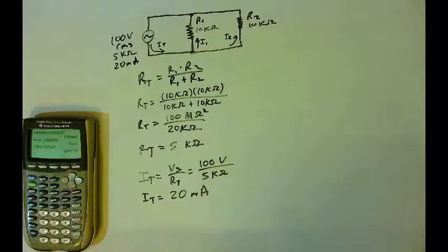The RMS value, being the equivalent DC voltage, accounts for that for us. And we only need to analyze the circuit when the current flows in one direction or the other. We don't need to do both. Okay, the RMS voltage already takes care of all of that for us. It's given us the effective values of the circuit.